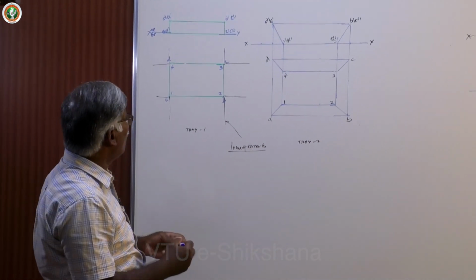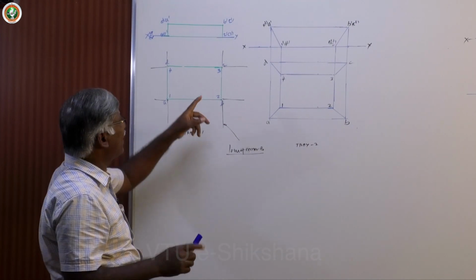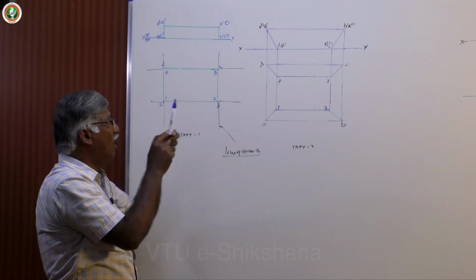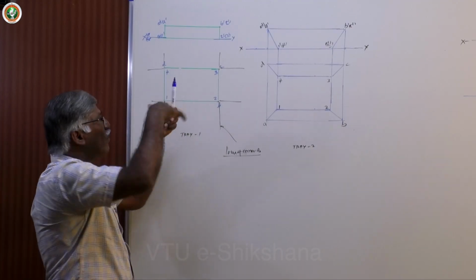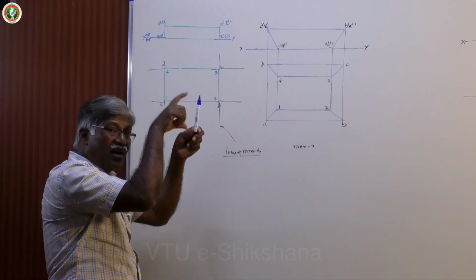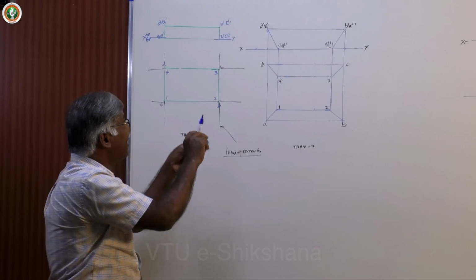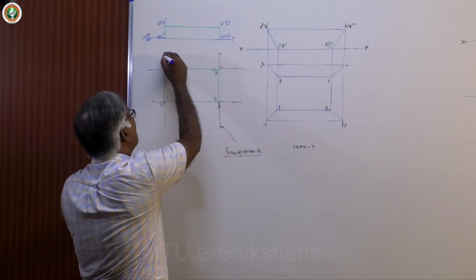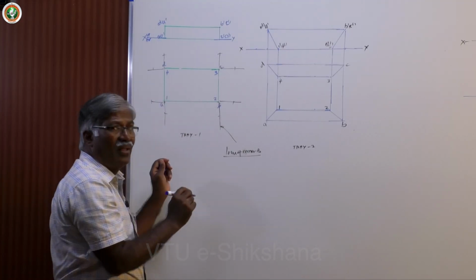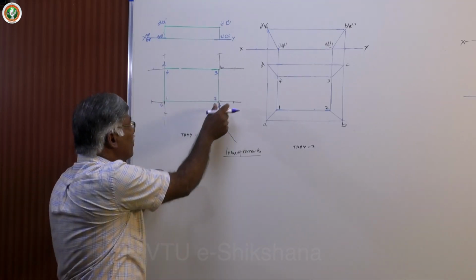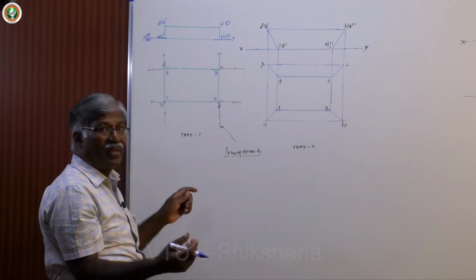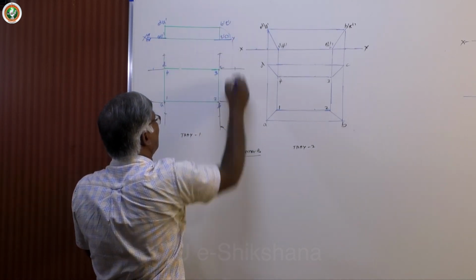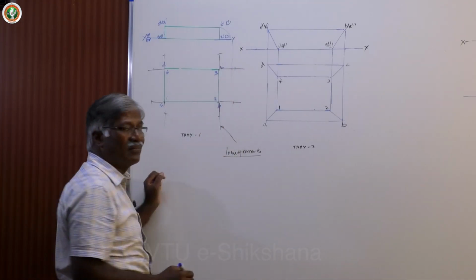Now, how to identify the height? It is very easy here because the line 2B or 1A, 3C, all are vertical. If you look at this, you will get true length only. So you can take directly true length from 2A center, draw arcs. That's all. All are equal. Say 4 centimeter. You take 4 centimeter, do it. Or as per the lines concept, you rotate this, make it parallel and project. You will get same points here. That also you can do.